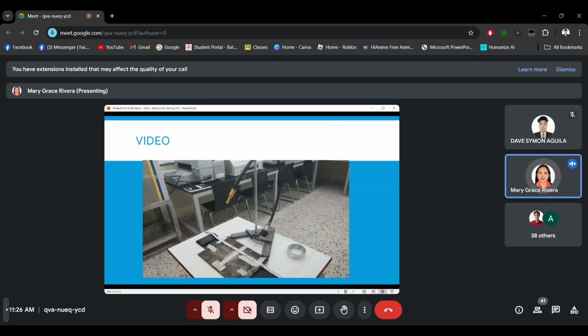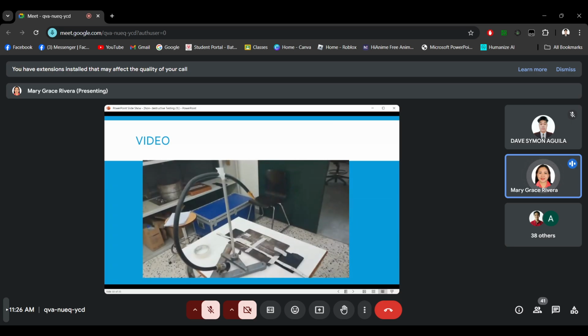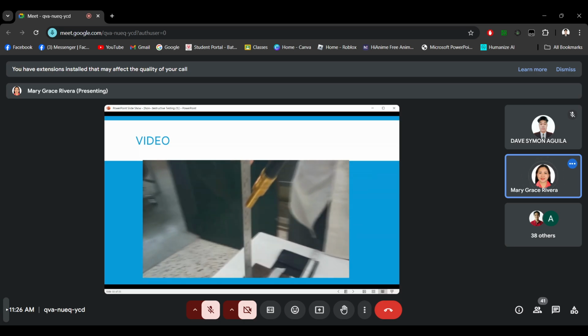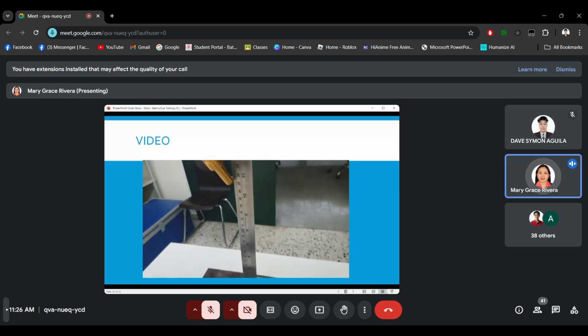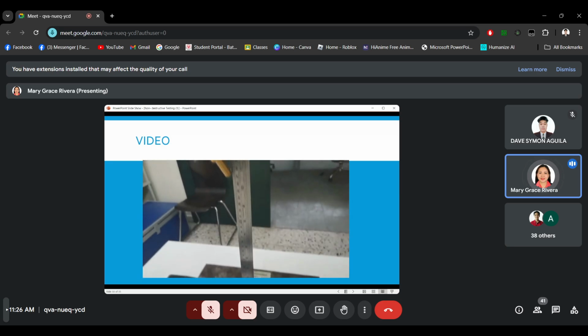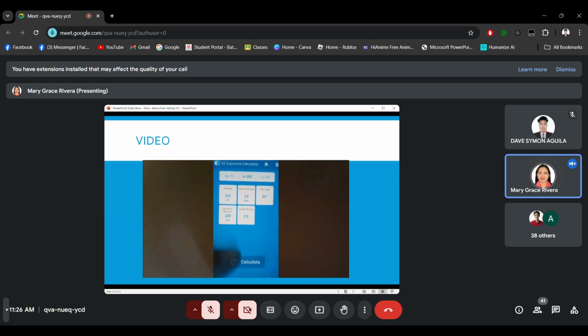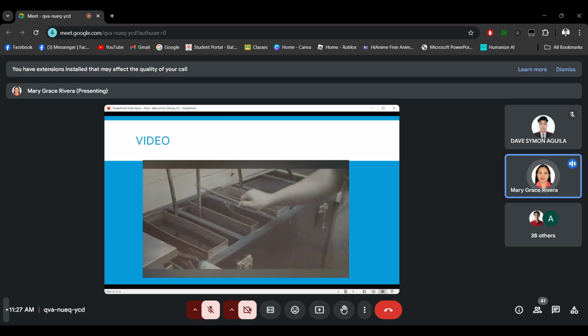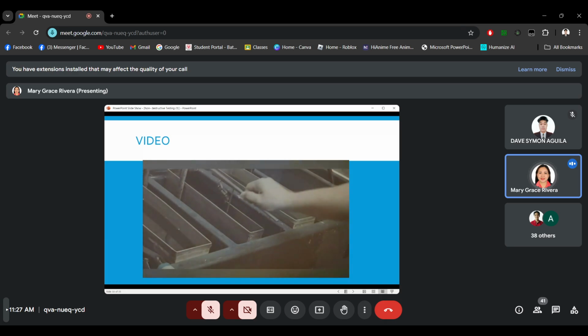Set the source at right angle with the film and weld seam using magnetic stand. Set the specimen at a proper distance. It should be more than the minimum distance that you can calculate by the rule. Calculate the exposure time by application. Process the films inside the dark room.